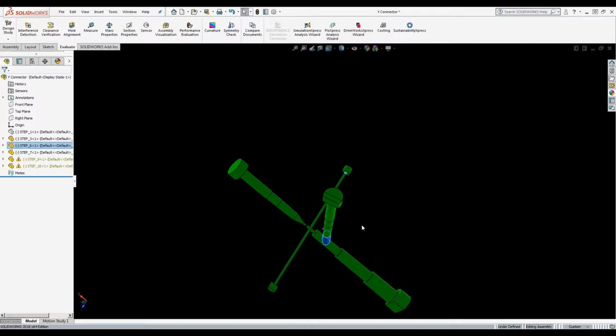Basically, the same assessment applies with this tool that's on the screen. It all is a hand-loaded mechanism, so the part comes out with the hand loads intact, and then it's demolded off of all the hand loads. So I understand the question, but with hand loads and it being a manual tool, there's no issues with collision or damage as it's being removed.